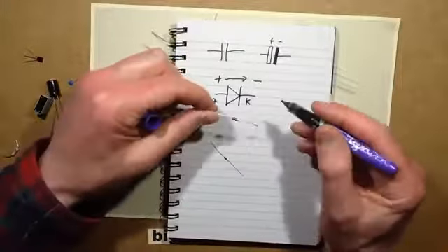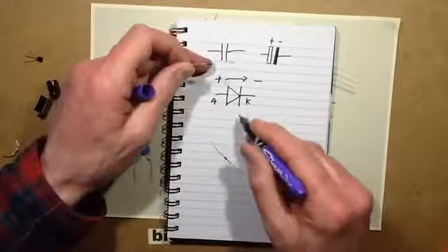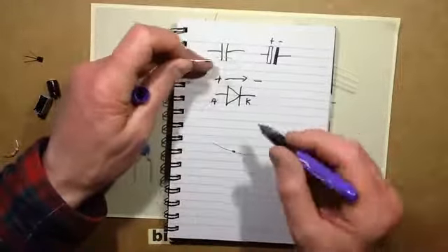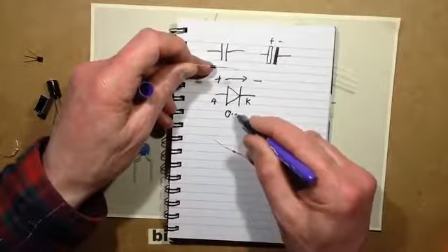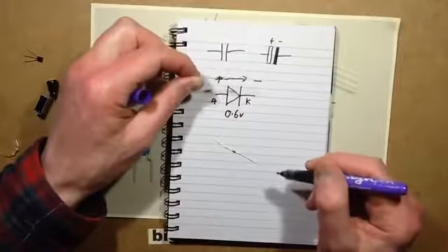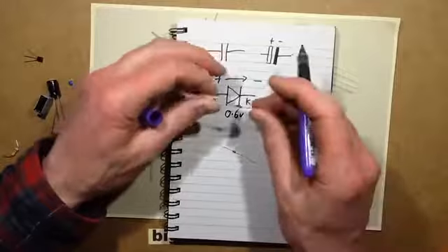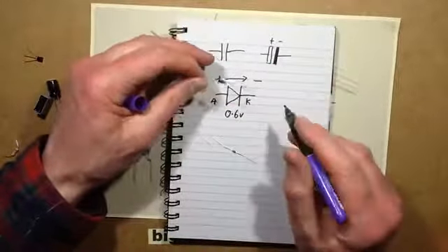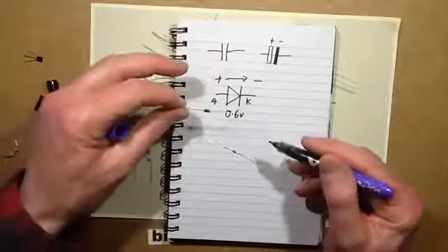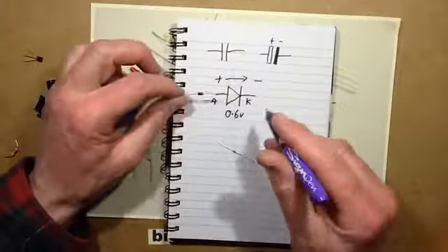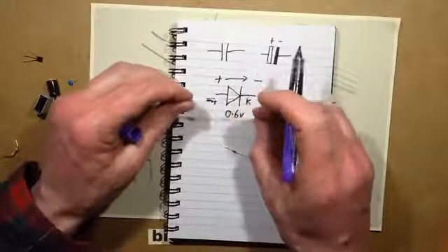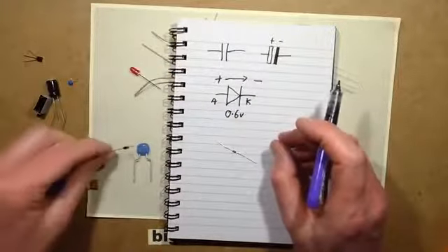This is a silicon diode, which, when it's forward passing current in the correct direction, positive to negative, will typically have a voltage drop of about 0.6 volts. Sometimes, it depends on the voltage rating, it'll actually go up to 1 volt, and it also depends on the current flowing through it. You get Schottky diodes, which have a much lower forward voltage of between 0.2 to 0.5 volts, and in cases of rectification, that lower voltage actually makes them much more efficient.